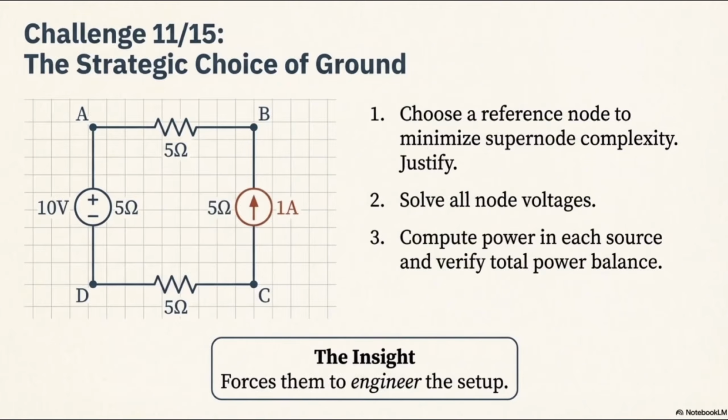In this condition, I'm telling you that first of all, ground is going to be a point that has the most connections to it. In cases where you have the same amount of connections to each node, you have to decide which place should be the ground. So if I consider this point as a ground, let's see what would happen.